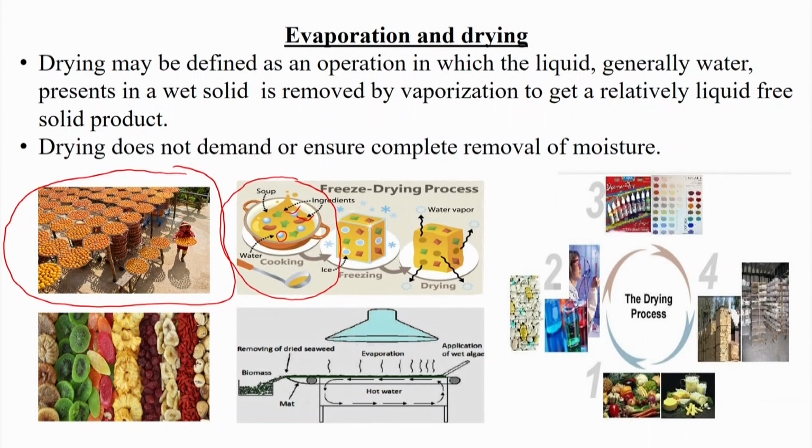But whenever we freeze this, whenever it is converted into a solid product from this liquid mixture, then the water also converts into ice. Then in the freeze drying process, sublimation takes place, that is, whatever water is there is separated from the system, or the solid ice is converted into vapor in a single stage.